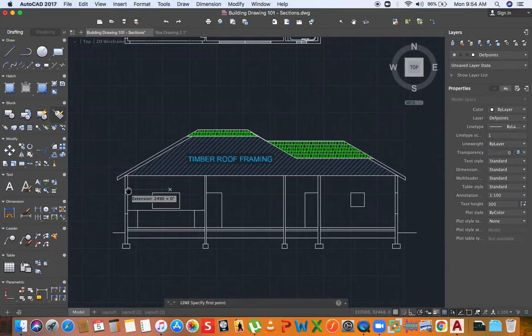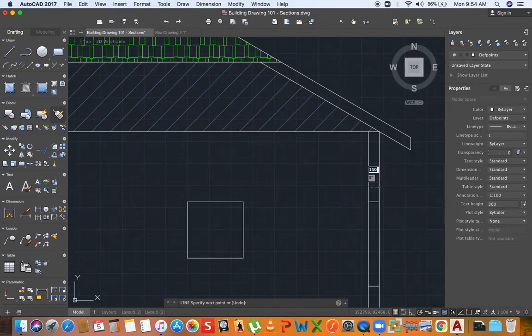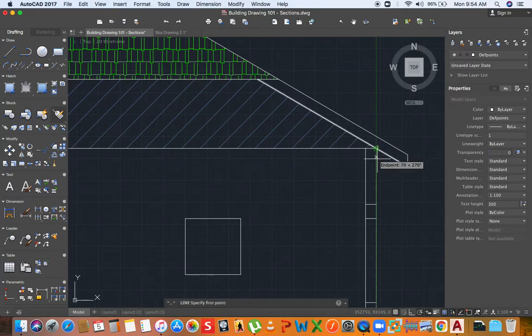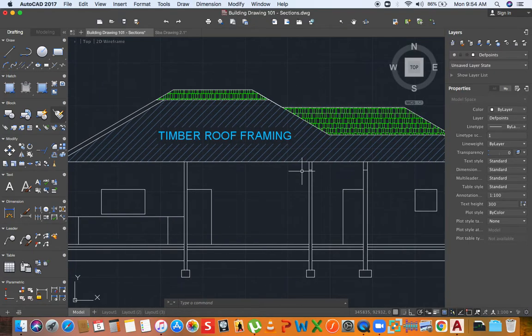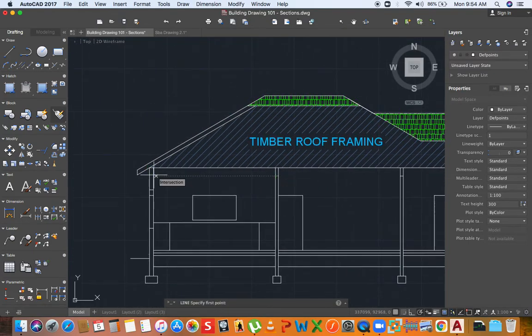Let me transfer this measurement. This represents the lintel that is over the door. And then you have another, the ring beam, 300 from the wall at top. You bring this on every wall, whether or not it has a window or a door. The roof has to rest on this at the top of the wall. Alright, so let's do some things here.